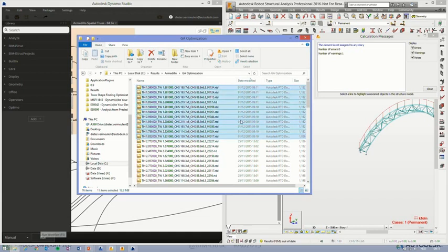What are these guys doing? Well, that's the Optimo stuff. That's a genetic algorithm. So the first one is this here, the assigned fitness results. So this one will take that objective function and it will calculate it. So it will run that specific function and it will allow us to take all the design variables, bring it into that objective function and return the results, and it will make a specific list of it. So let's just generate something already. Let's run this one.